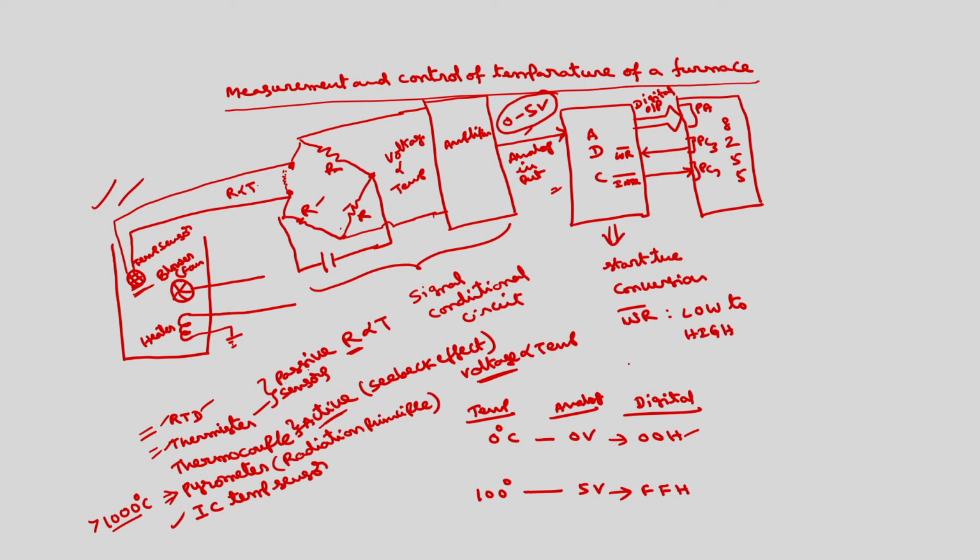Then if this INTR bar is 0, it implies the conversion is complete. Otherwise, the conversion is not yet complete, and the microprocessor simply waits.